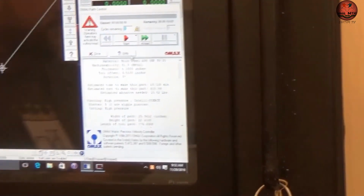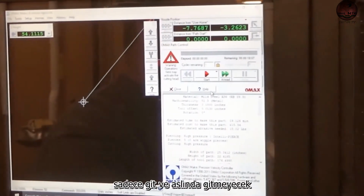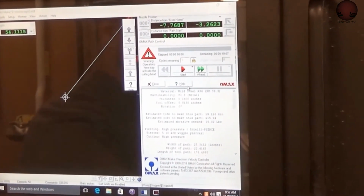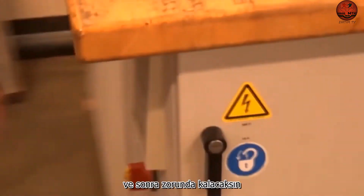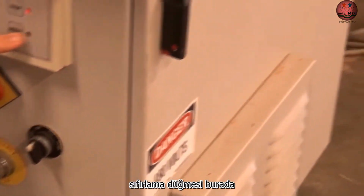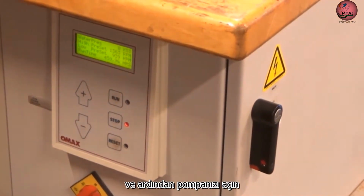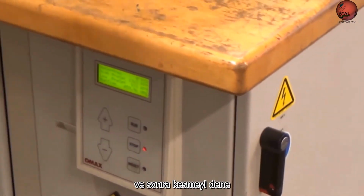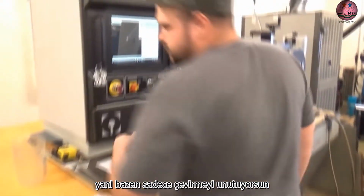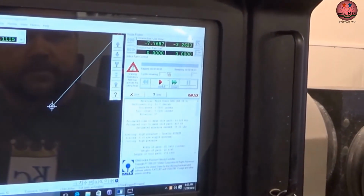Now let's say I forgot to turn my charge pump on. It's actually just going to go, and it's not going to do anything. And what you would have to do, you'd have to stop it, go back home, and then, say it's already off, you'd have to press the reset button right here on the control board. You'd have to reset it, and then turn your pump on, and then try to cut. So sometimes you just forget to turn the charge pump on. So I'm going to go ahead and press start.